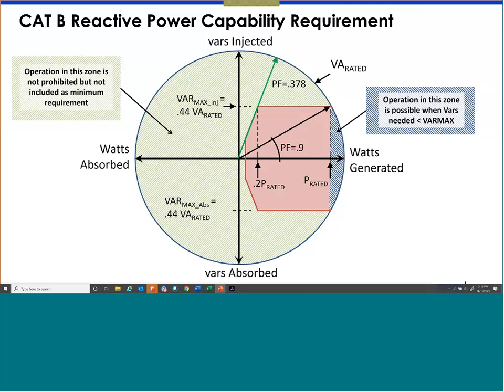Recently, we are doing a project, again, the same example that I gave before, a transmission connected system for nighttime reactive power support. We didn't work directly with the inverter manufacturer, so we don't know the exact story. But what we are seeing is that for that particular plant, which is not their latest model, the inverter has to go to the sleep mode in the evening, and then come back again in the nighttime mode. So there has to be a transition of the mode between normal daytime mode and the nighttime mode, which should not be the case if it was designed for that from the get-go.